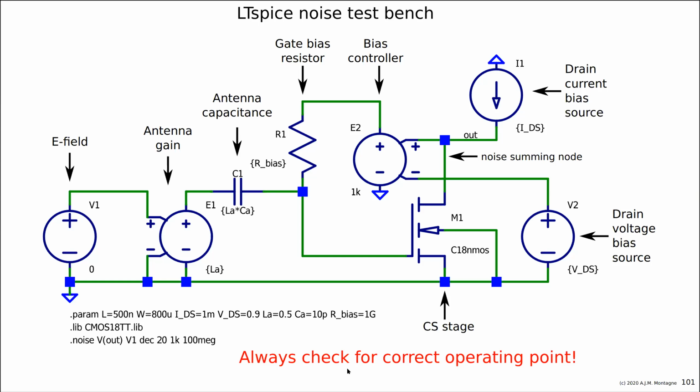And what I forgot to mention: using a circuit like this, you also have to check the frequency response at the low side. The high side is not interesting at all, but the low side is limited by the resistor here that is also noisy.